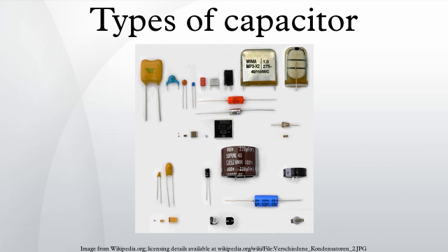The leakage current drops in the first minutes after applying DC voltage. In this period the dielectric oxide layer can self-repair weaknesses by building up new layers. The time required depends generally on the electrolyte. Solid electrolytes drop faster than non-solid electrolytes but remain at a slightly higher level. The leakage current in non-solid electrolytic capacitors as well as in manganese oxide solid tantalum capacitors decreases with voltage connected time due to self-healing effects.